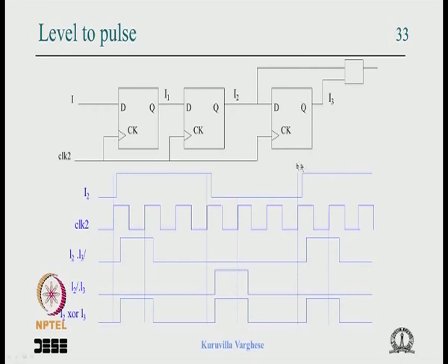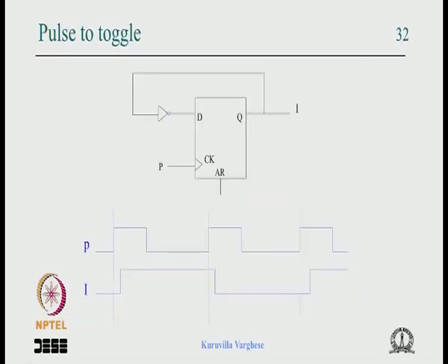So this generates the proper timing as far as the state machine is concerned, because the state machine is working with the same clock, that is the assumption. So I hope you got this picture. It is a very useful structure which is very much used in synchronizing clock domain crossing. The only difference is that I have manipulated this a little bit, and when this pulse is coming from a domain with another clock, then there could be a slight change in the circuit. The pulse can go here in the data path, but the clock of the domain comes here. It is a very slight change.